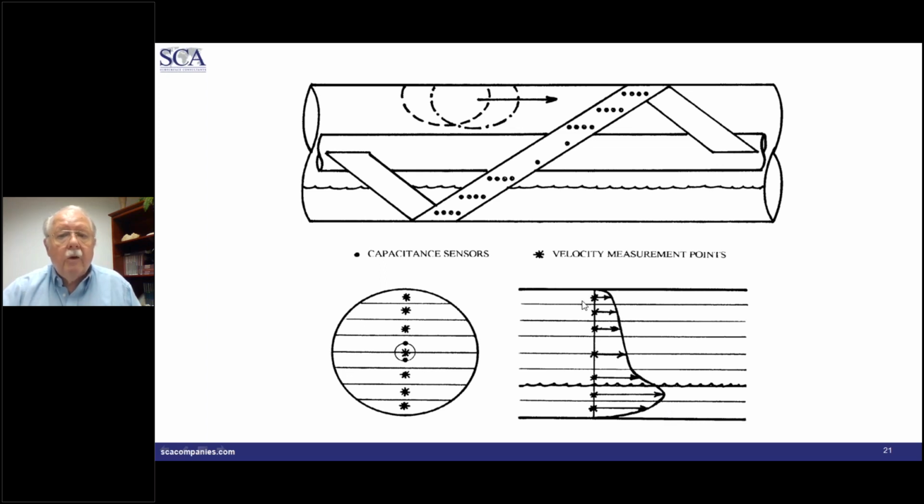Now you wonder maybe what that spinner was at the front. This is a velocity profile measurement right here. So we have 7 velocity measurements, which give us a very credible velocity profile across the wellbore. Notice that this velocity profile will actually detect these slugs. The leading edge of the slug will come, and the trailing edge of the slug will eventually come. That slug will detect the presence of gas until this one over here goes by. It'll detect gas here, but obviously it will not be detected over here.